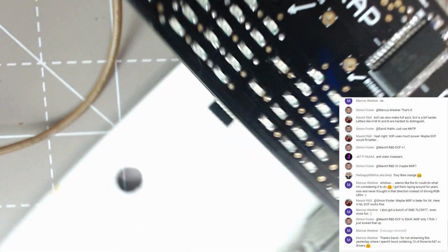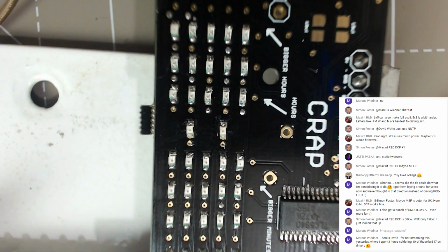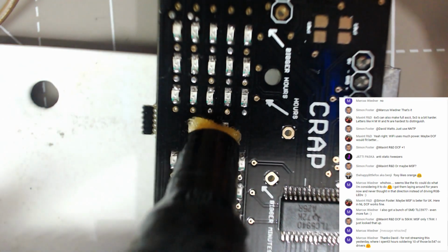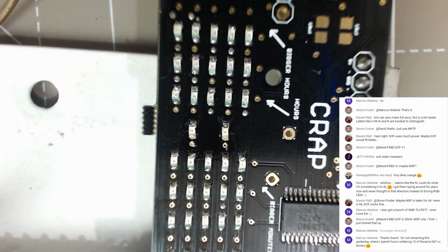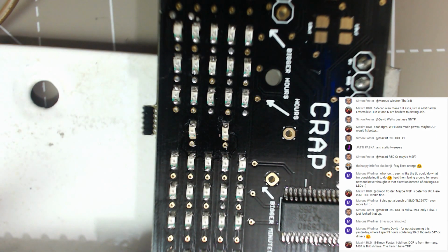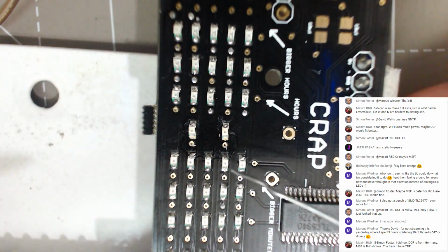Now let's switch this around a little bit and we'll solder off those last 2 bits there. They felt a little bit off actually there. The solder didn't really apply very well, so I'm just going to use a little bit of flux just to help it along. It's probably because the board's been sat out for a while and got a little bit of my finger oil on it, I guess.